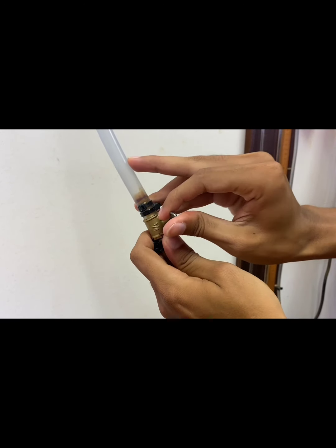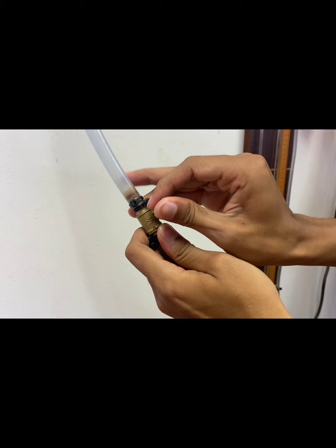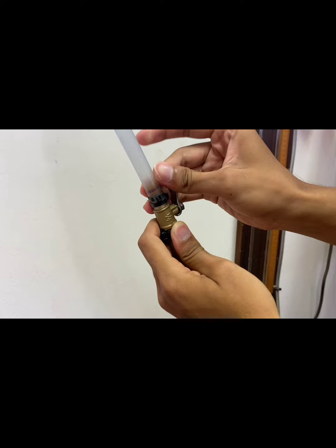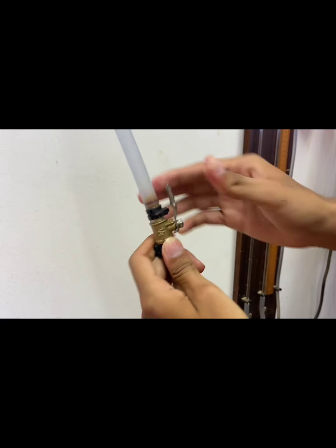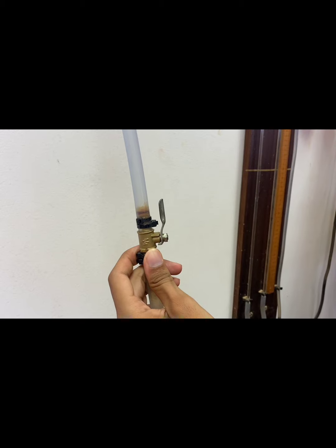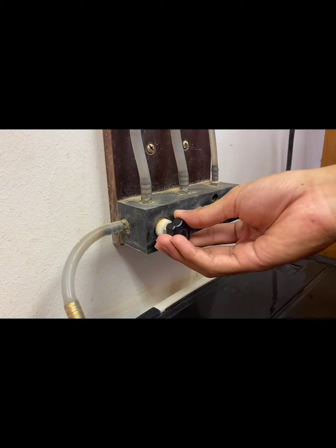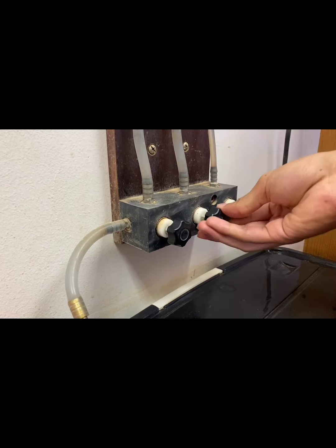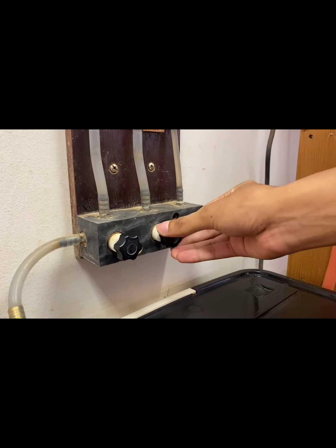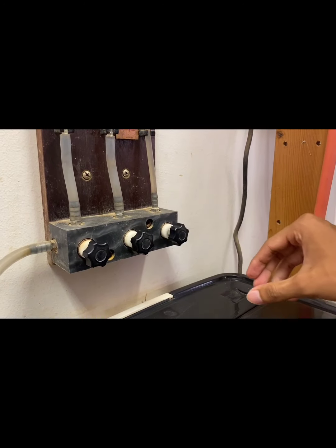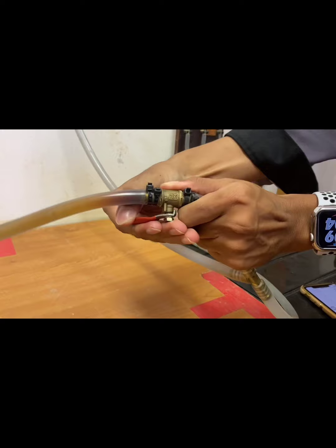Firstly, open the valve and fill the water into the standpipe to mark the initial height of the standpipe. Record the initial reading for height H1 and time T1 before the commencement of the test. Open valve 1, valve 2 and valve 3 to make sure the water in the standpipe falls down. After that, close the valve and start the test by observing the flow of water and the time of the reduction.